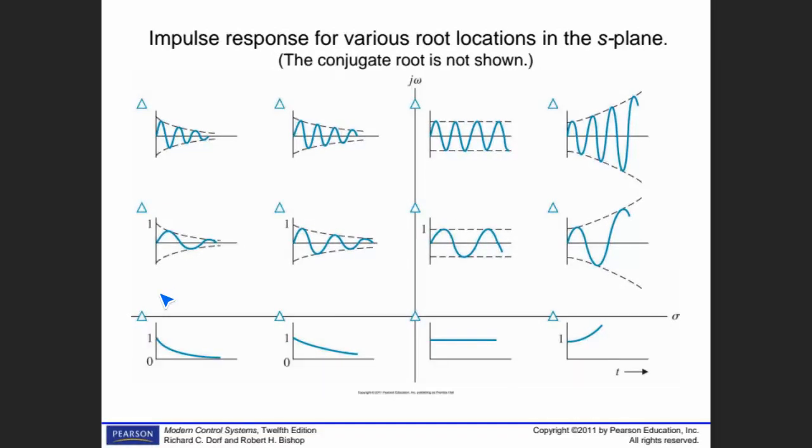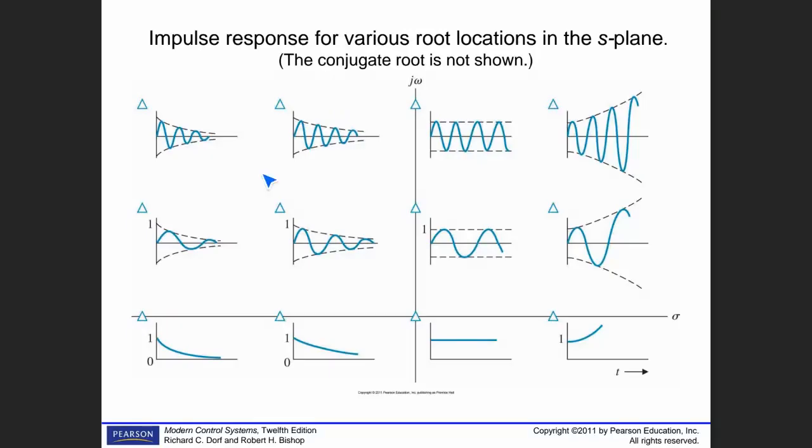These are far away from origin. The transient response is very high. So the effect of these poles is diminishing. I repeat, the effect of those poles is diminishing faster than those poles. That's why these poles are called dominant poles. So if we are going to neglect between those, you are going to neglect the faraway ones.